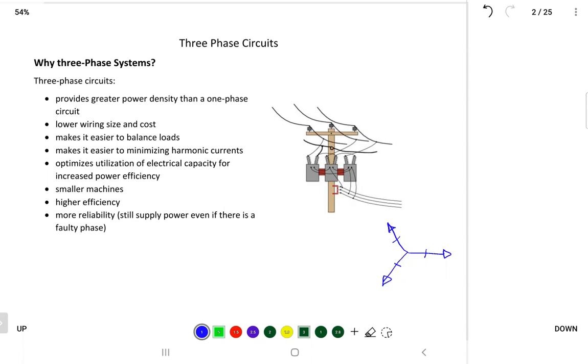That's a balanced 3-phase. So if you say this is phase A, B, C, and by the way, A, B, C means if you are moving in the anti-clockwise direction, you move A in the anti-clockwise direction, you'll find B comes behind A. When you move B, you'll see phase C coming behind B. So that's the sequence that we're dealing with, we call it the A, B, C sequence. And in power systems, this sequence is known as the positive sequence.